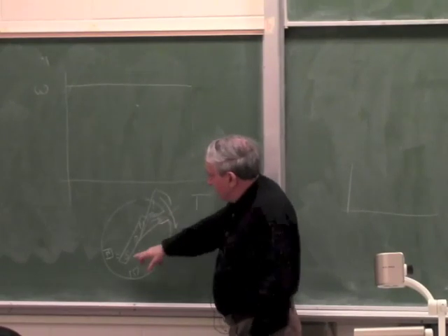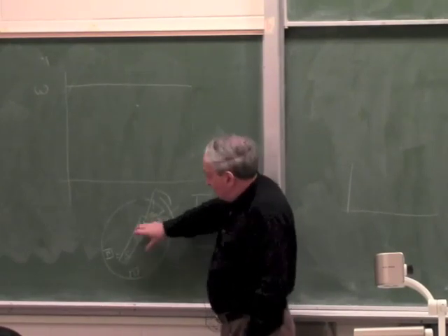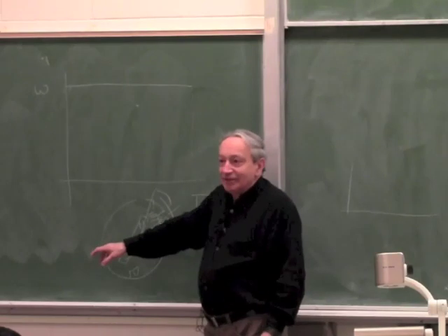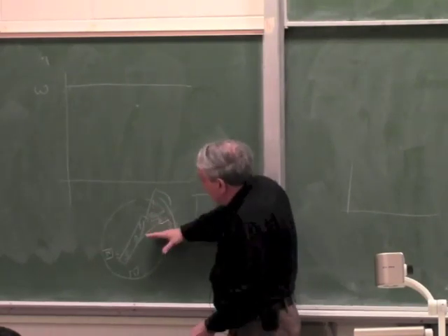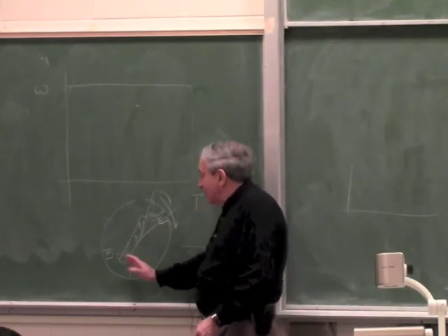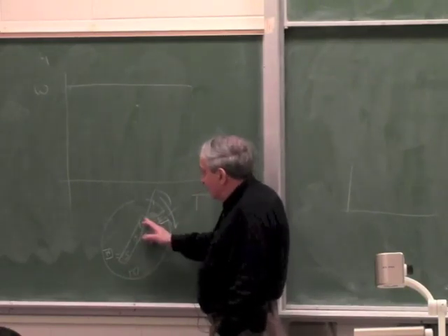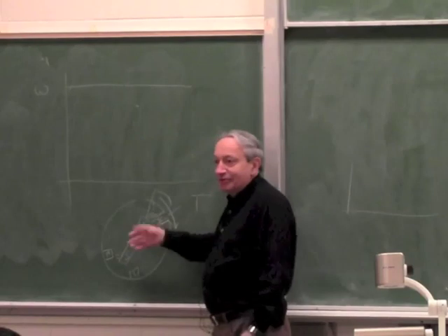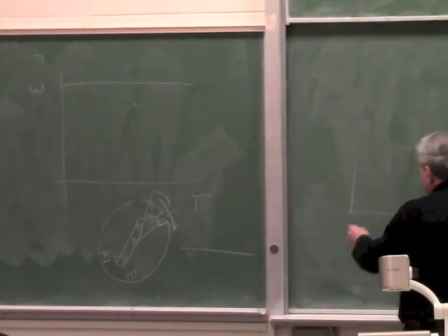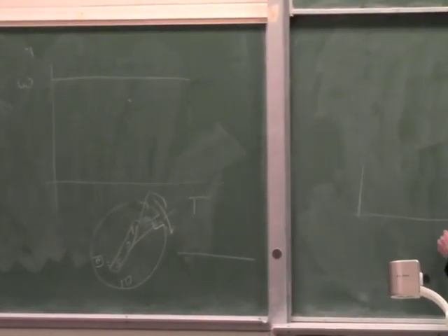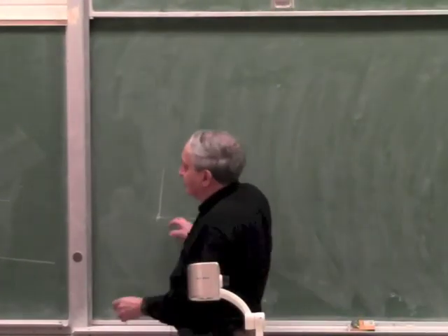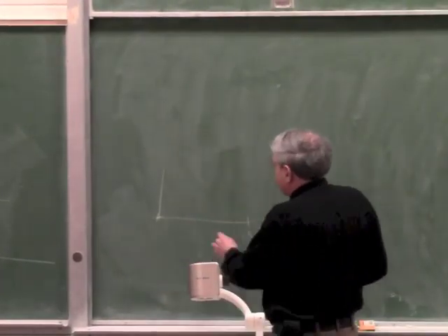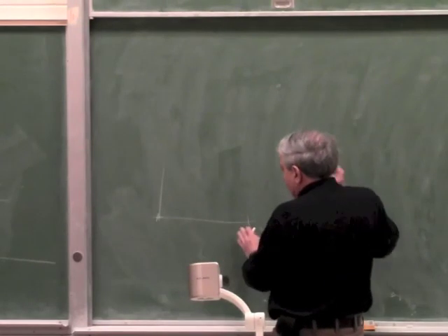If this S ends up here, it wouldn't attract this pole anymore; it will actually repel it. So the torque at a power angle of 180 degrees has to be 0, and at 0 it is also 0. Now the reason for the power angle, so again, I'm drawing something else now.